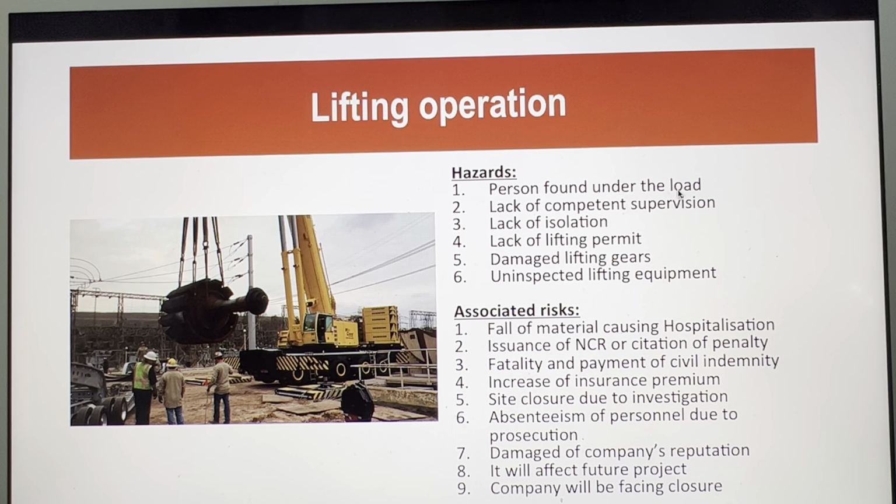So, person found under the load while doing the lifting operation, lack of competent supervision. We have third-party training for lifting supervisor, lack of isolation, lack of lifting permit, damage of lifting gears, uninspected lifting equipment. Now, the associated risk here is fall of material causing hospitalization, issuance of NCR or citation of penalty, fatality and payment of civil indemnity, increase of insurance premium. Of course, when the insurer finds out that you have more fatalities in the year, the following year the premium will increase. Site closure due to investigation,